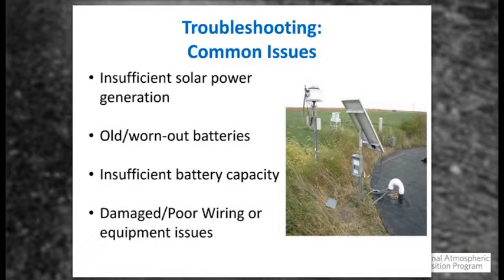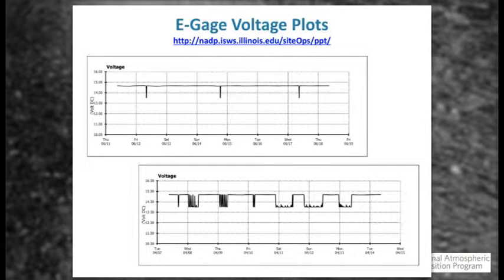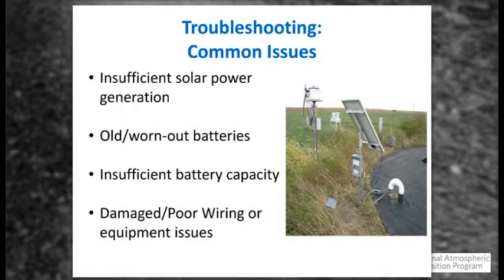Next slide, please. I'll just add one last thing on the wiring. Every connection is a way to lose energy, and you're trying to conserve energy here because you're limited. So check each connection too. A lot of these low voltage things, you think, well, it's safe, I can just wire tape things together. Make sure all your connections are good and sound. Just because it's low voltage doesn't mean your wiring shouldn't be of good capacity, because that's just wasting energy that you have very little of. You need to have good quality cables and connections everywhere.